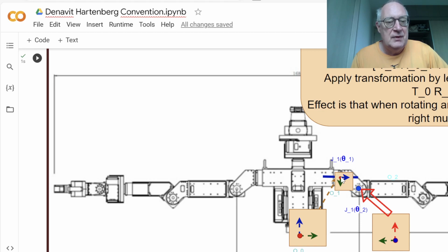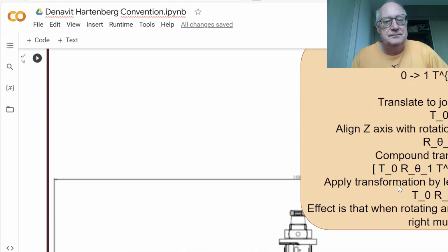The other two frame axes we could rotate around the z-axis if we wanted to, but I aligned it in such a way that x remains forward and y points downwards. And for this joint here, our z-axis is pointing outwards, and x and y are aligned in such a way that they're pointing upwards or to the left.